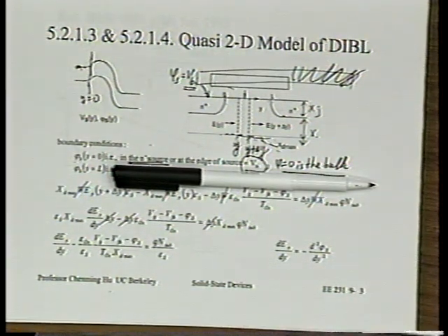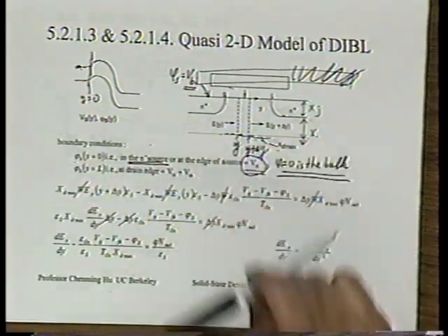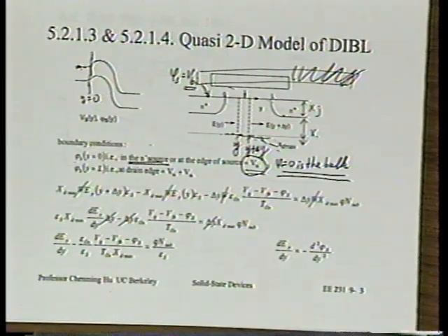It's a little unusual, but I'm forcing you to think. The potential in the N plus source is not 0, it's VBI. Knowing that, what is the potential in the drain, given that the drain source voltage is known, of course? So what is it? It's VBI plus VDS. Isn't that right? It's not difficult, right? All right. Good? All right. Very good.